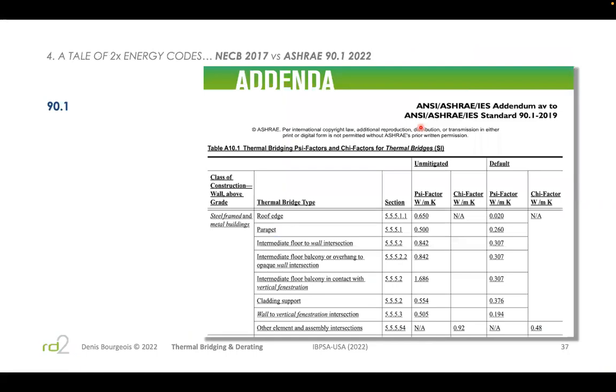Okay. Well, I'm going to continue. I don't see that there are any questions, so I'll be continuing on the fourth step here. So as a demonstration, I'll be trying to compare ASHRAE 90.1 2022. So basically that's addendum AV to 90.1 2019. So this will be part of the 2022 code requirements. So this will affect the prescriptive requirements, ECB, Appendix G, and there are additional ways of doing those calculations.